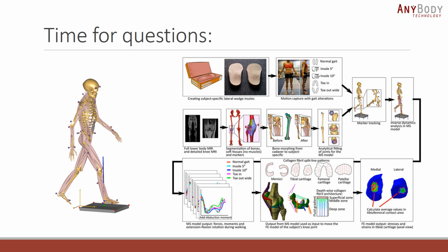We did a simpler representation than in the finite element model, like an elastic foundation model, and the ligaments are also modeled as non-linearly elastic, as we do in the finite element model. So it's a simplified representation of the finite element model inside the musculoskeletal model, and then we pull the loads out of that. So we don't have the full finite element model in there, but a simplified version of what it captures. Yeah, I think that explains it a bit.